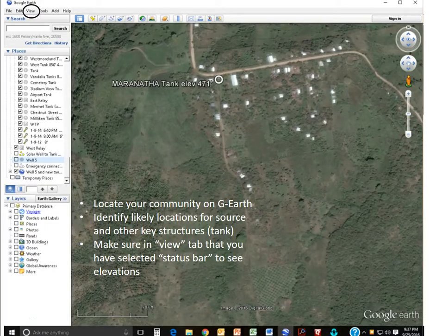This PowerPoint is intended to help you get through the very initial stages of using EPANET. First thing you need to do is get a decent map that you can put into the EPANET program. I use Google Earth because you can get a picture of just about anywhere. You can also get rough elevations, but you have to convert the Google Earth image over to a bitmap, and I will show you how you do that.